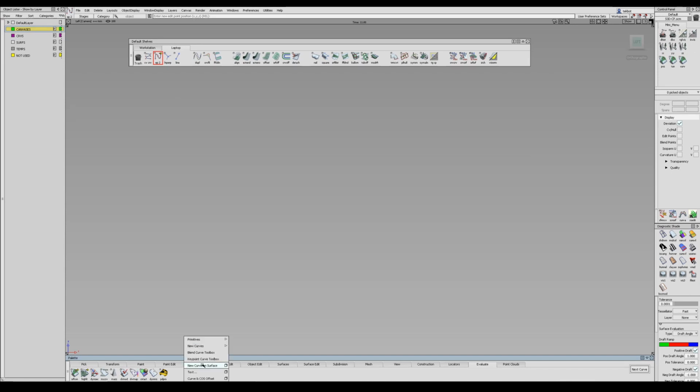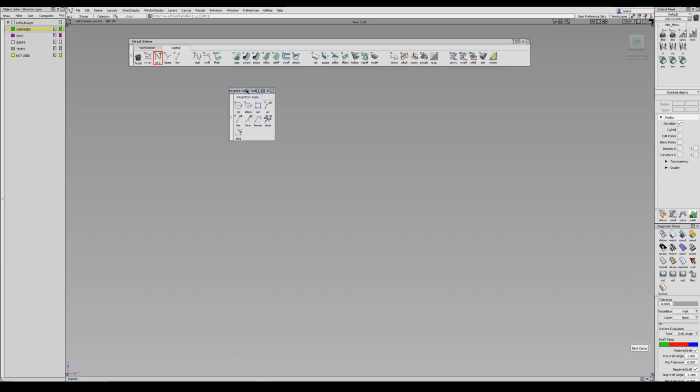The next one is the perpendicular to object with the key point curves. Key point curves have some really useful features. I don't recommend most of these. But for example, under this menu is the perpendicular line, and then also the line tool. And these are just fantastic. The perpendicular line gives you a line that's perpendicular to whatever you snap to. So that's great for really controlling the layout of your curves or placement.